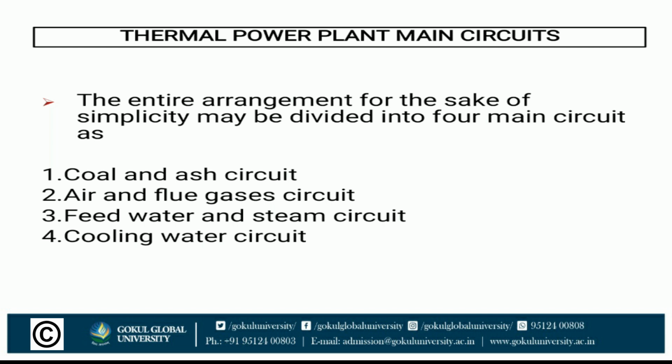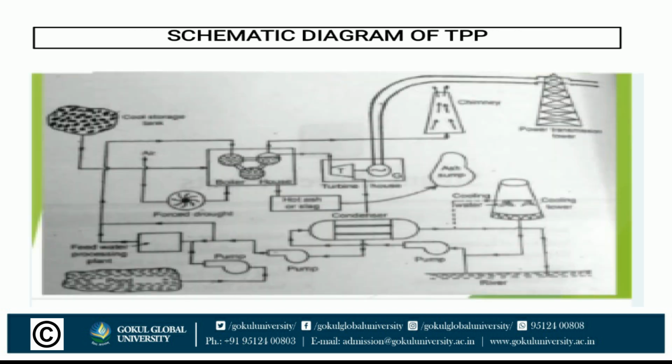In the boiler, water is converted into high pressure steam which may be wet. The wet steam gets superheated when it passes through the superheater. The superheated high pressure steam is supplied to the steam turbine. The steam first expands in the high pressure stages of the turbine and then expands in the low pressure stages after being reheated in the reheater, until it is brought to its original dryness or superheat.